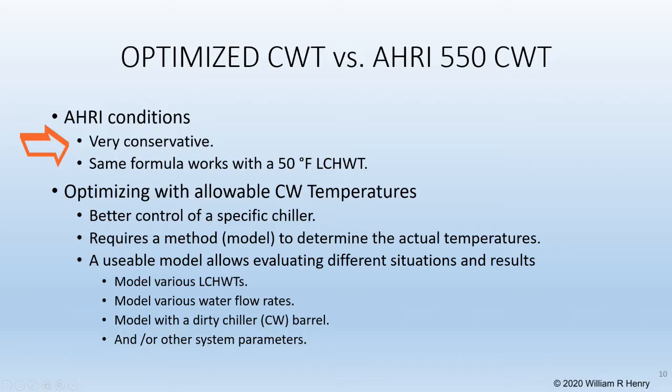As shown, the AHRI profile for condenser water reset is a very conservative approach, but the typical chiller operation can see even greater performance gains if only the most efficient condenser water temperatures are known. So we need a method or tool to determine the lowest allowable condenser water temperature under any given set of conditions.